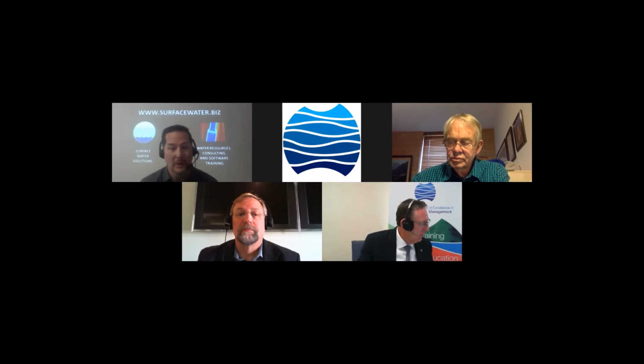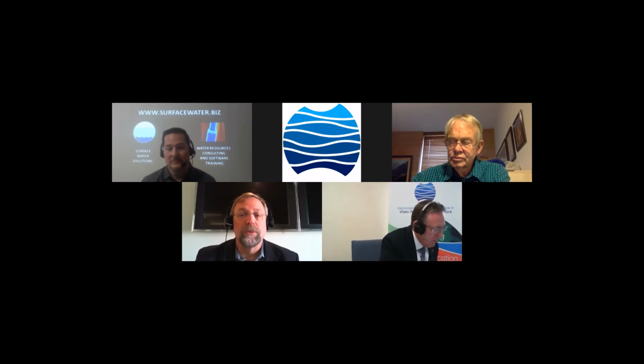In some cases, you can get beautiful animations, but when you look at them in profile and section view, you'll realize that there were a lot of instabilities that just got pushed right through the model. I would clarify, you can usually get those instabilities worked out with the choice of roughness values along that lateral structure between the 1D and 2D. You do need to consider what type of interface that is. If your flow is crossing natural terrain, you're going to have to adjust those roughness values down low.